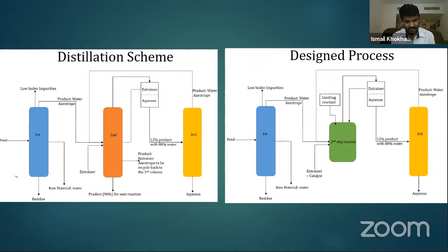All this data starts getting generated, and once you are done with all this, the next step is deciding which method to use, like McCabe-Thiele or the FUG method or Ponchon-Savarit, and then the number of stages and everything is decided. But this way you will be able to design satisfactorily, you can say 100% efficiently, once you have all this data in hand. So data generation for a process engineer is very important.